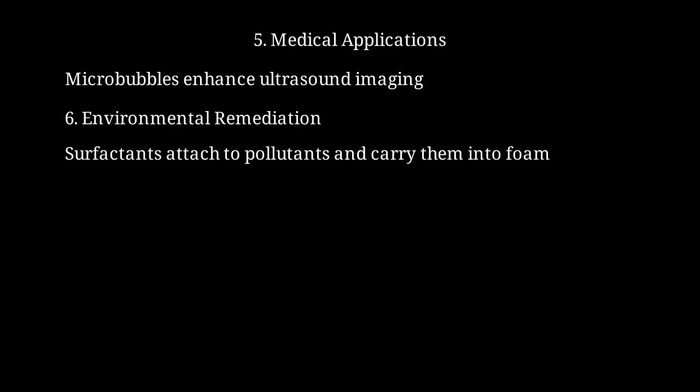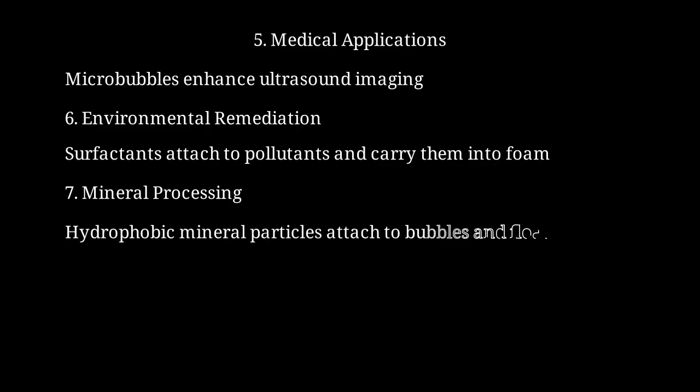Sixth, environmental applications. Foam fractionation is used to remove pollutants from water. Surfactants attach to pollutant molecules. When air is bubbled through contaminated water, the pollutants concentrate in the foam, which can then be removed. Seventh, mining and mineral processing. Froth flotation separates valuable minerals from ore. Selective surfactants make desired mineral particles hydrophobic. These particles attach to rising bubbles and float to the surface, while unwanted material sinks.